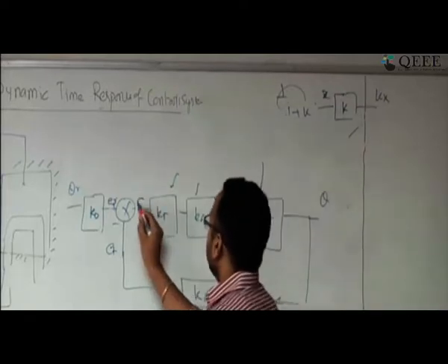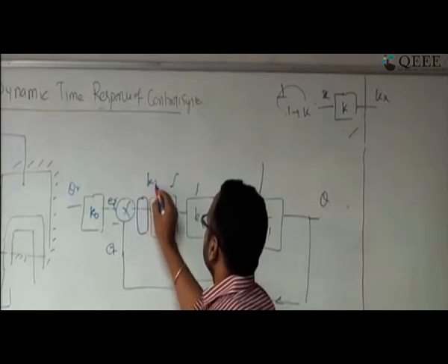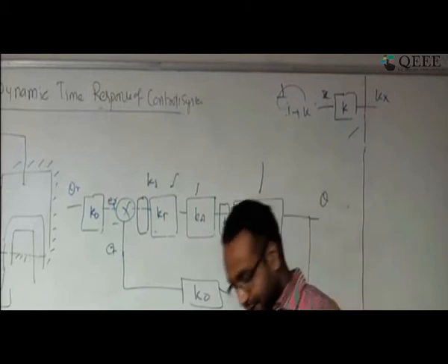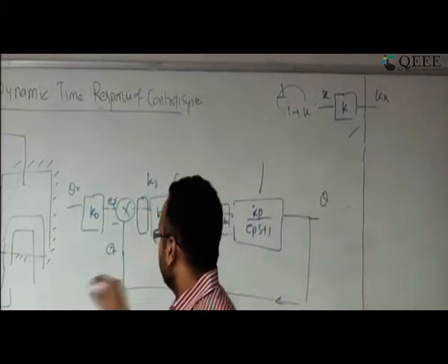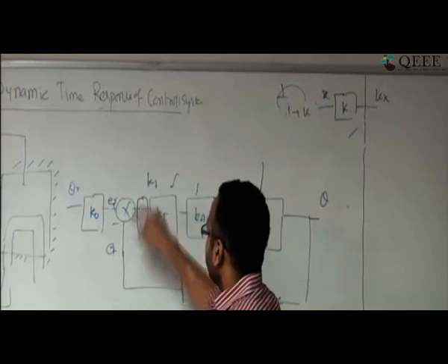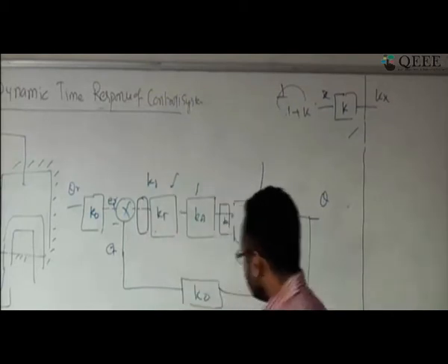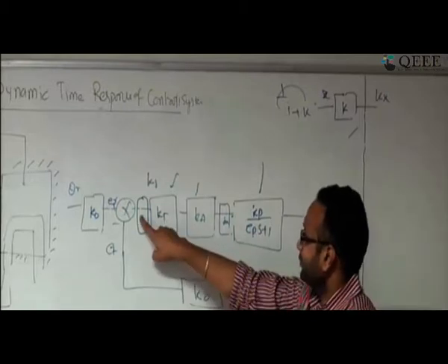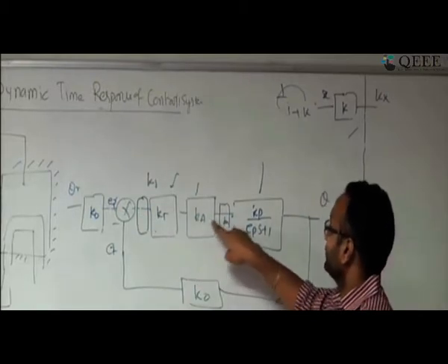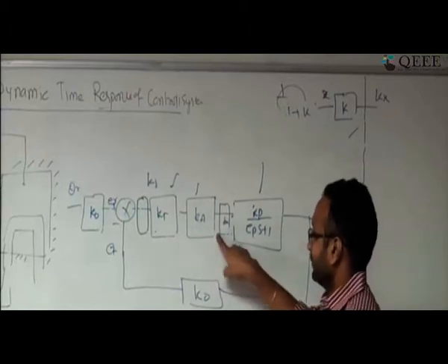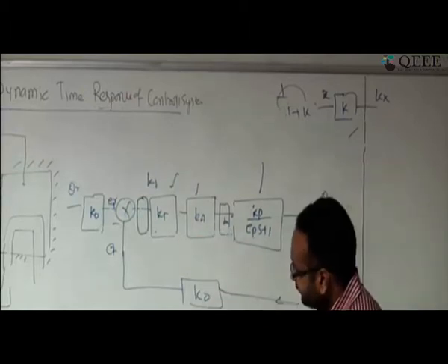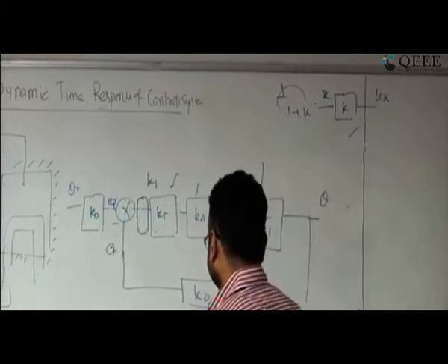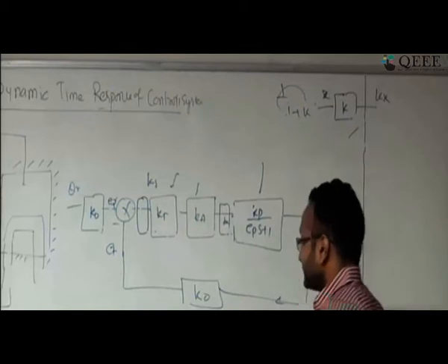Here I am adding a proportional constant, also like K, which I have mentioned. When you talk about the proportional controller, you know that this U is going to be proportional to the error. So let me add that as K here. The entire thing is fixed in the Kp, because Kp is a multiplication of the proportional constant into transducer constant into amplifier constant into offset valve position constant. The entire thing is fixed in one part, and only the variable part is the K of your proportional controller. Okay, fine. So this part is clear.